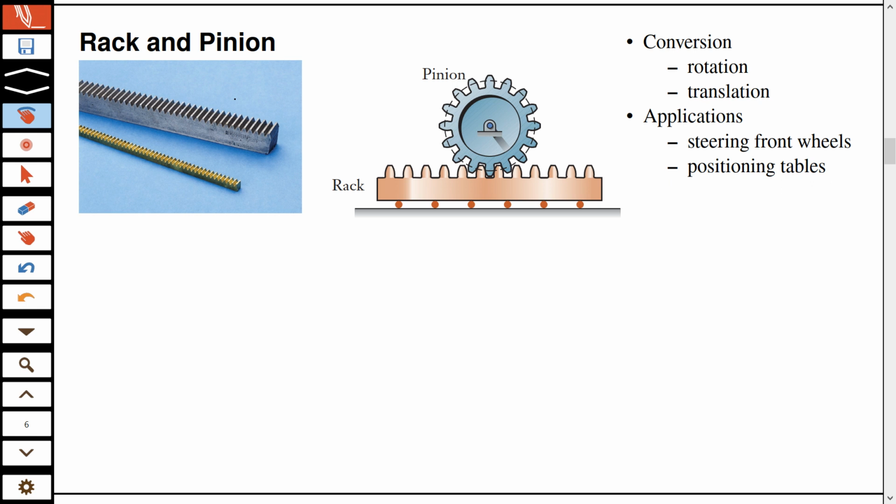So that was spur gears. Okay, the next type you will see commonly is the rack and pinion. You remember pinion? What was pinion? I introduced pinion in the previous slide. It was the driver. So these are two gears. The pinion gear is the one which will drive the other one. So this will be connected to the effort, and that's why you are calling it a pinion. But the load, the follower in this case, is called a rack because it's straight.